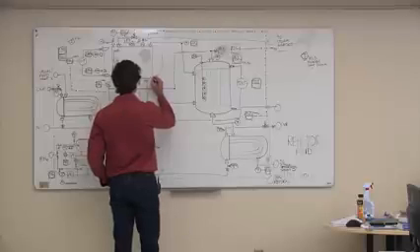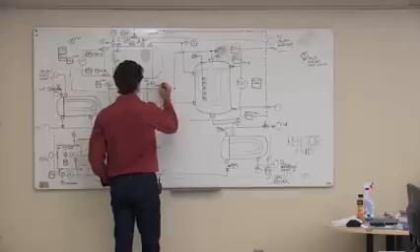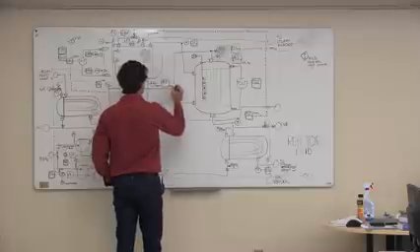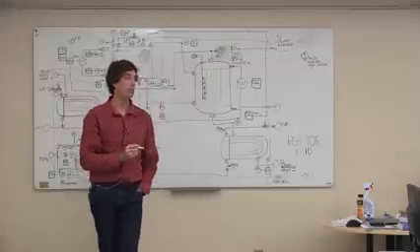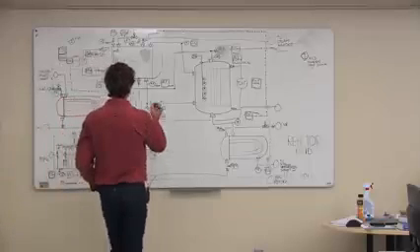So we could put a nozzle in, or we could pull it off here. Let's pull it off here maybe. Analyzer element, conductivity, analyzer indicator, conductivity. Yep, we could do that. Missed a line.